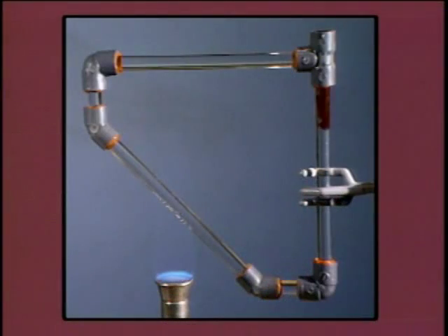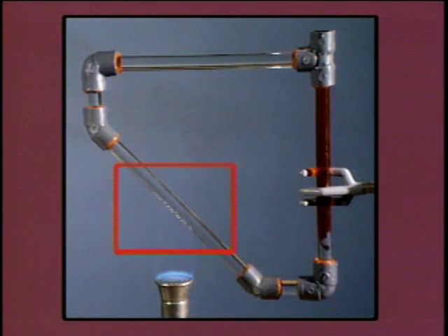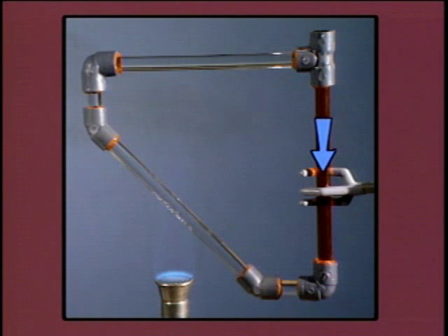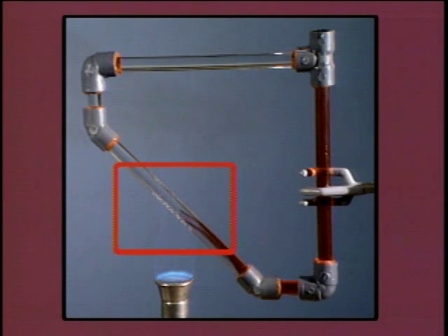Fluid movement is often divided into two categories: natural convection and forced convection. The type of convection depends on what produces the fluid movement. We've set up a loop to show the principle of natural convection. When we heat one side of the loop, the fluid in that side gets lighter, that is, less dense. The warmer and lighter fluid rises. It's replaced by cooler, denser, and therefore heavier fluid coming in behind it. The difference in density between the warmer water and the cooler water starts the flow in the loop.